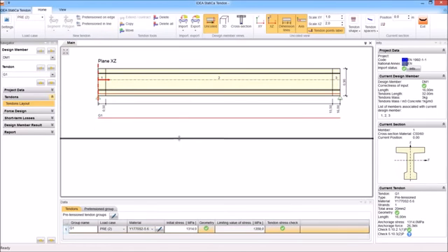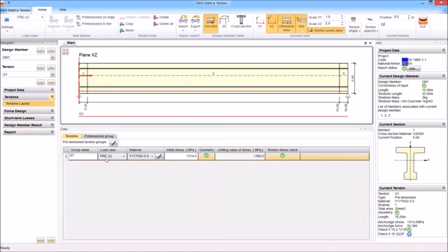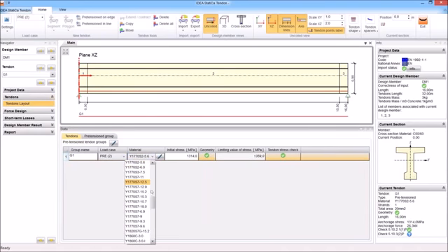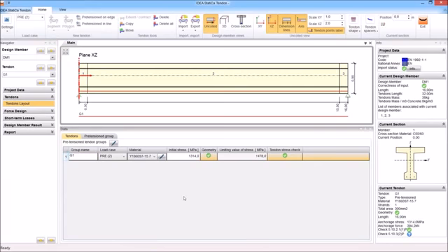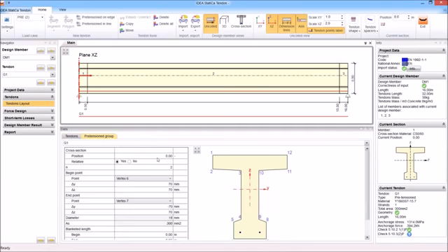Here in the data window, you can see our predefined pre-stressing load case. The program selected the first tendon on the list. My tendon will be Y860, this one. And I can go to the definition of the geometry. I know, either from some preliminary calculation or from my experience, that I will have 5 strands.